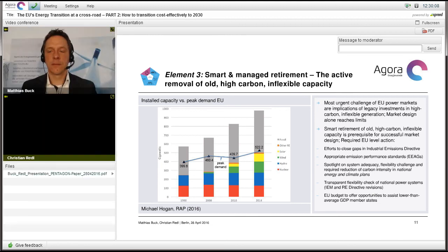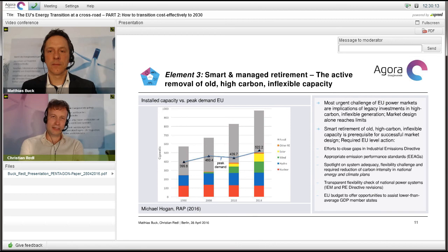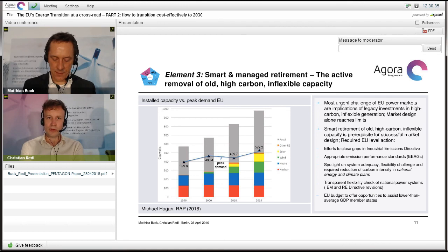Yeah, thanks. It's a very good question. It also has, I think, several dimensions to it. First of all, increasing interconnection is indeed important to tackle the flexibility challenge from a ramping point of view. So, for example, if you take the hourly ramps of wind power in a domestic power system, and then compare the overall European wind ramp that emerges at the same time, if you integrate all the countries on an integrated energy market, you see that these hourly ramps are reduced by half. So through integration, you basically get rid of 50% of your flexibility challenge, which is of course very sensible.